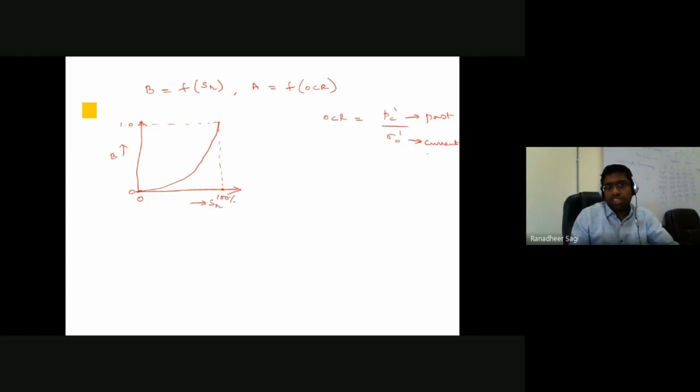Okay. So at present, how much is the effective stress getting developed in the soil sample? In the past, what was the maximum stress that your soil sample has experienced? So once that data is known, I can calculate the over consolidation ratio of that particular soil. So depending on the over consolidation ratio of the soil, your so-called A parameter, Skempton's pore water pressure parameter, at the failure of the soil sample, people do also write it, instead of writing it as A, at failure, that Skempton pore water pressure parameter A as AF. F there indicates it's the failure, at the failure of the soil sample.